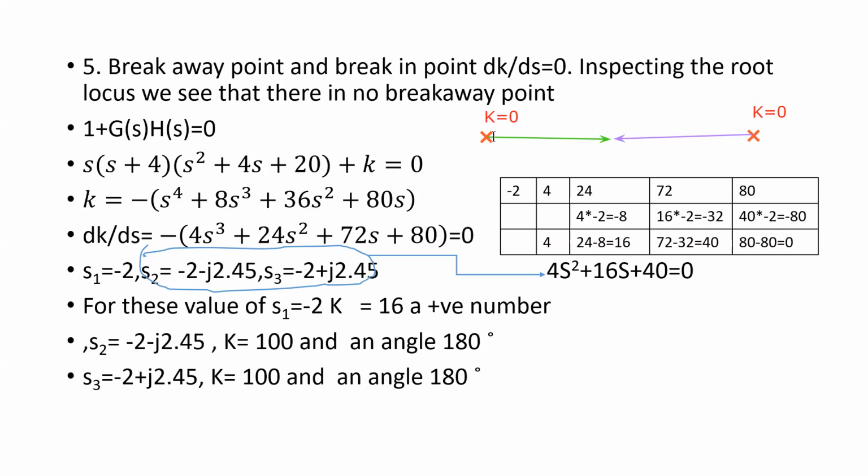Your root locus will start varying. It will take a trajectory. It will start giving different test points, and you're joining those test points. So somewhere here the value becomes maximum when these two meet. So at this point they break. It has to break and it has to go. So now what will happen? This will break and go up like this, whereas this will break and come down like this. So it requires a breakaway point.